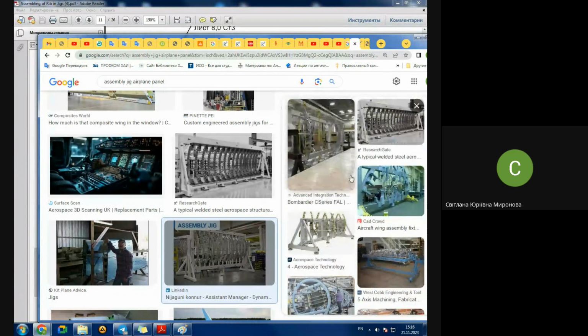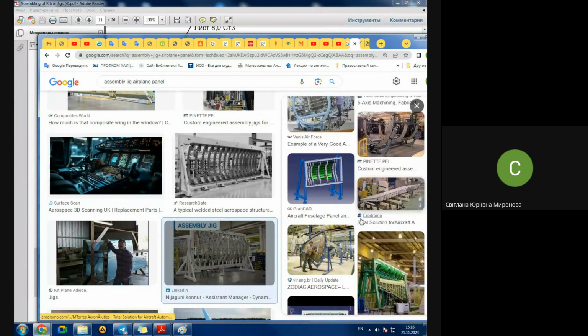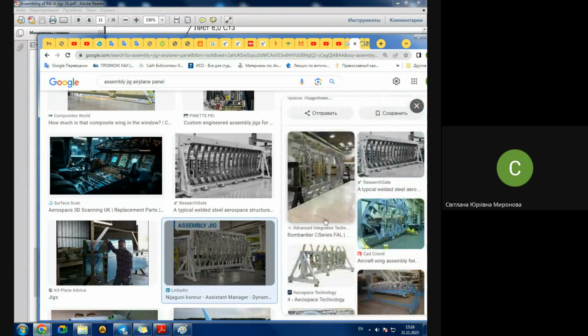When it comes to the hole for pins, you need to pass the same hole sometimes with different instruments. Each place, drilling, next one countersinking, another countersinking, increasing diameter and increasing accuracy. Reaming, one more reaming, and finally you spend some minutes for each particular hole.